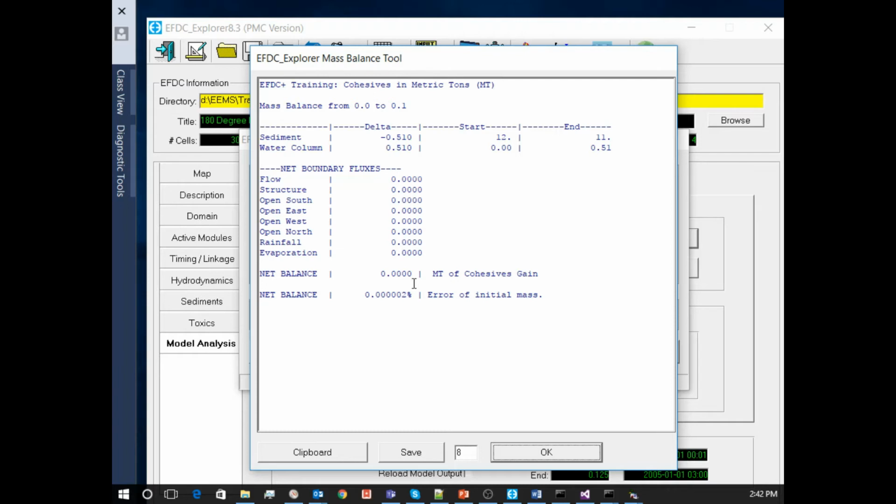Yeah, well, you almost definitely will. On a reservoir, you have to remember that flow gauging is plus or minus 10%. With an ADCP, it's 5%. But if you're using an index gauge system, that could be worse.